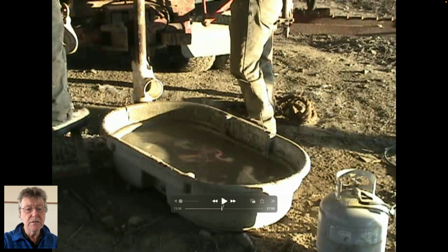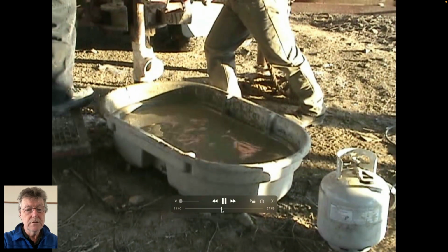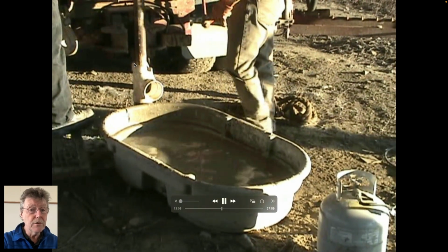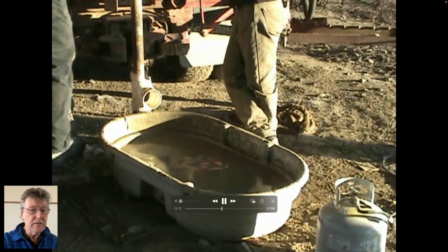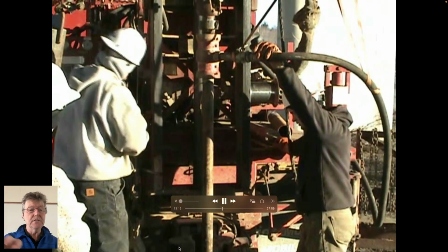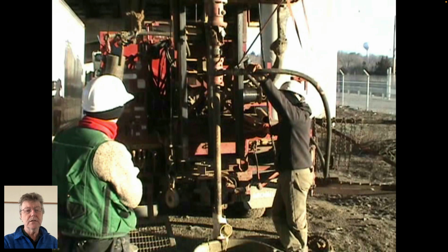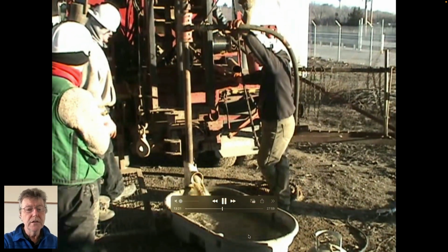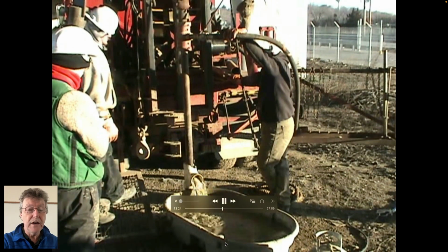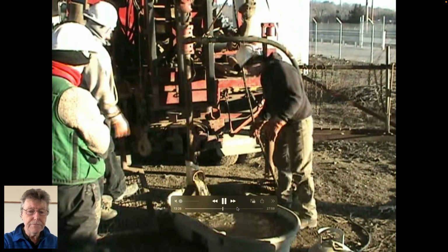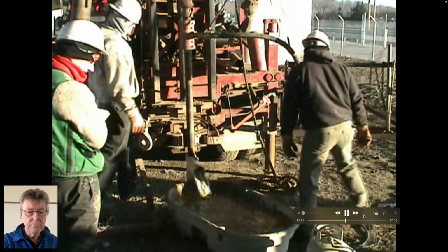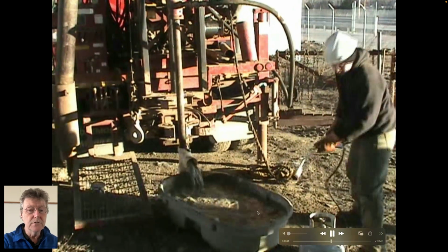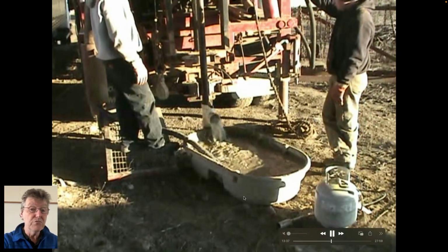We don't really need that, but you've seen this before. This is the drill still going into the ground, water circulated along its length and then returned out of this T-bend into the bucket, into the bath, as you see going there. The supply of water to the hole is sucked back out of this bath. You can see a couple of things on here which isolate the end of the bath, to stop the cuttings going down to the end and to have clean water that you recirculate.